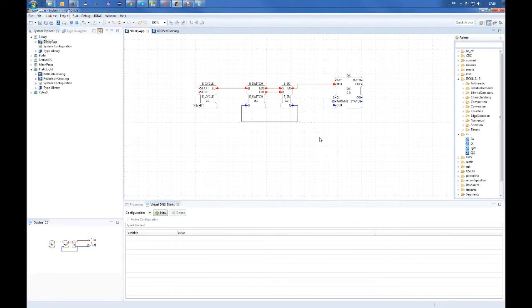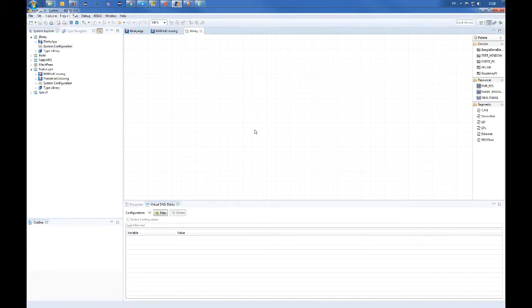If we had a simulation environment now, we could directly test if this is working. But I want to show it to you on the real hardware. So I go into the system configuration, and I take a BeagleBone Black as hardware. This BeagleBone Black comes with a parameter called manager ID. This was developed in the IEC standardization phase as a way to specify how the engineering tool, 4diac IDE, can connect with the device.